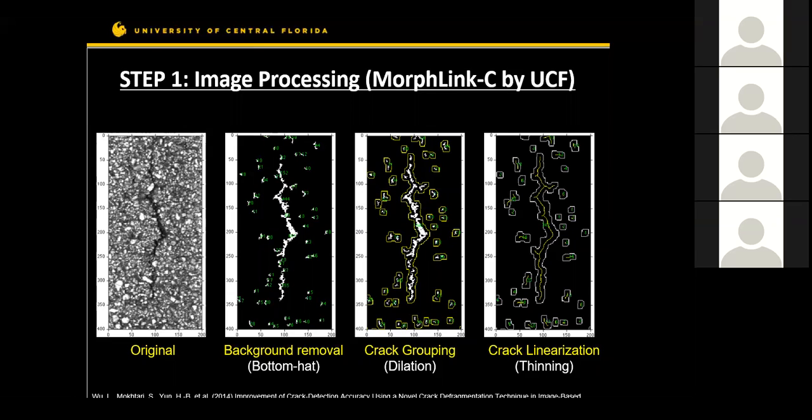They propose the morphological dilation technique. Boundaries will expand and the crack will join. They did an extensive study to find the parameters and prove their concept. And at the end, a thinning transform can be used, so we can have an abstraction of the crack for the direction or calculation of the length.